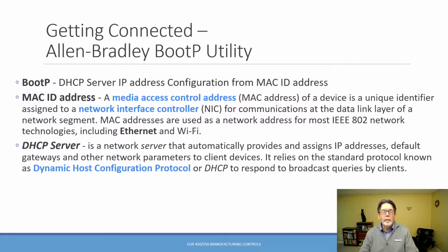So we would want that configuration in the port manager we were just looking at. We would have to switch it back from static IP address to automatically accepting an address assigned by the DHCP server. And we need to know how to switch back and forth in order to program Allen Bradley PLCs.